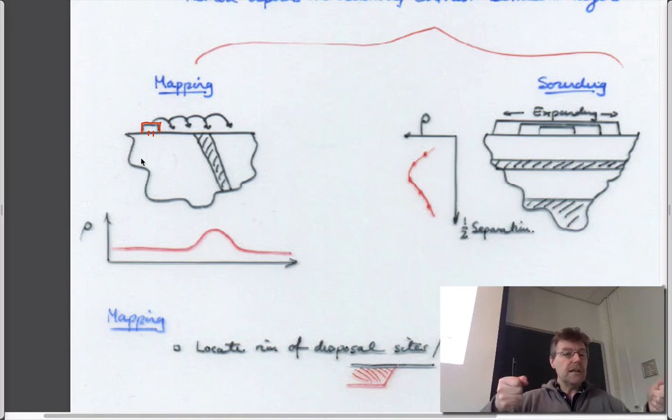You'd pull up all these stakes, you'd physically move it to another location, and then you'd do the measurement here. And then you do the measurement here, then you do the measurement here. And so what this would tell you, if this is able to tell you something about the electrical conductivity, or resistivity, in this particular place, is how, as you went from one location to another, that electrical resistivity might change. And you'd be able to pick up this bed without drilling, without looking anywhere in the subsurface, but you'd be able to pick this up. So that's one way of doing it, which we'd call profiling.